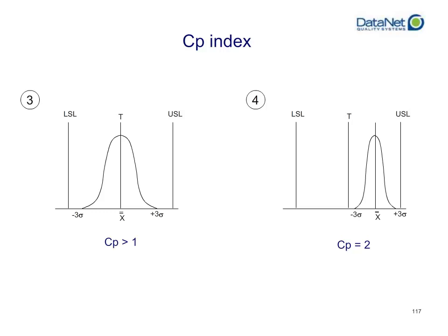Now you may notice on this particular slide number 4, unlike the other 3 slides we saw previously, there's something that should be obviously, glaringly a problem here. You could theoretically be producing twice as much good product if your CP is 2 than if your CP was 1. However, that doesn't necessarily mean you're producing within specs, and it doesn't mean you're not close to producing data that's out of spec.